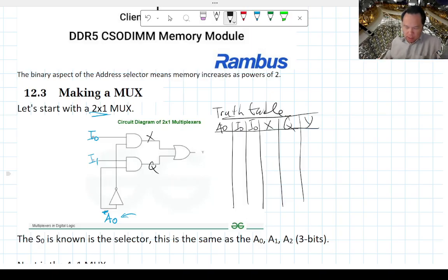All right, if everything is 0, then you have 0 coming into this. I'm going to draw a little circle here with a dotted line. It's not a real NOT gate, just so I know which input is inverted. On the first gate you have 0, 0, and the AND of 0, 0 gives you 0.